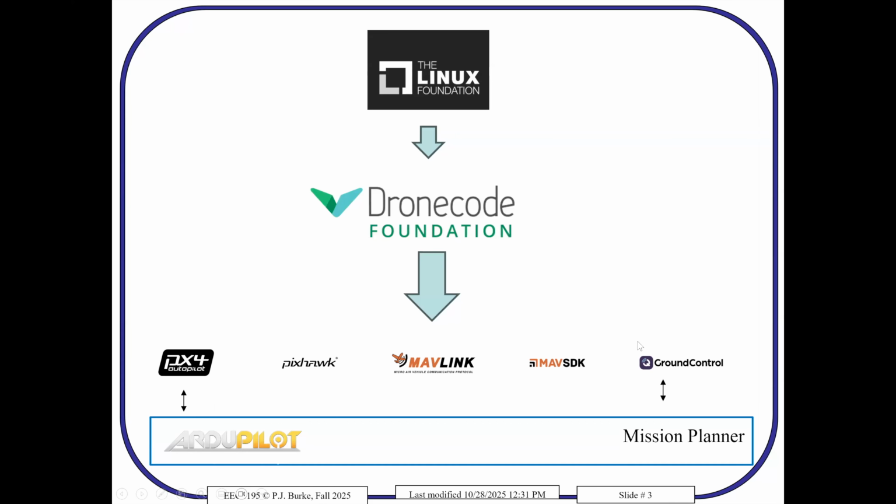And then there's Q Ground Control, which is a ground control station that's open source, just like Mission Planner. So all these are open source. Mission Planner and Q Ground Control are both ground control stations. Q Ground Control is available also on Linux, Mac, and Android and iOS. And I don't use it in this class because it is less familiar to me personally, and I believe it has slightly less functionalities for all the parameters and mission, but it's more or less equivalent.